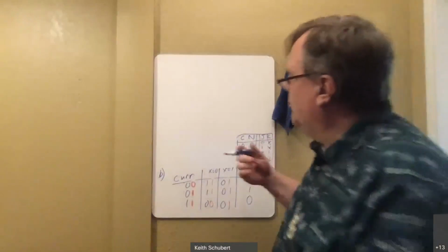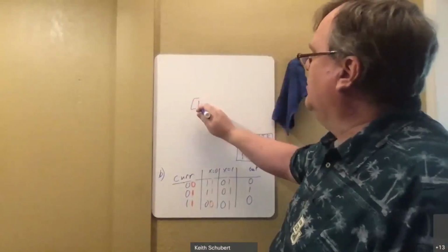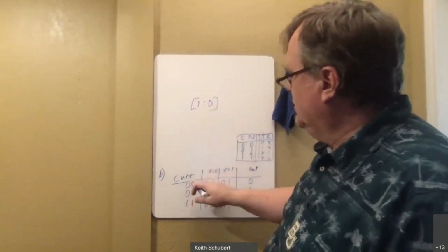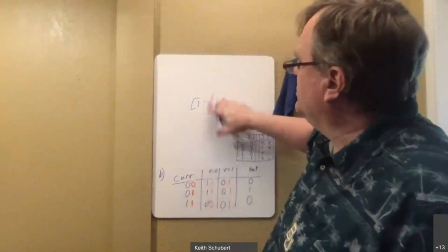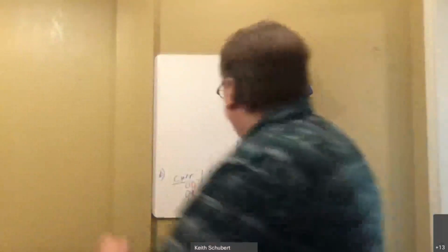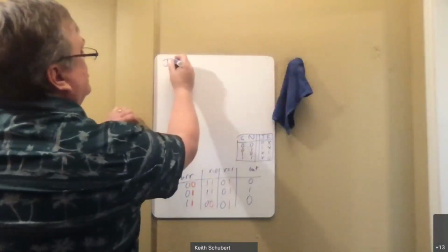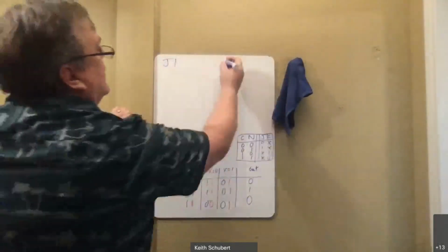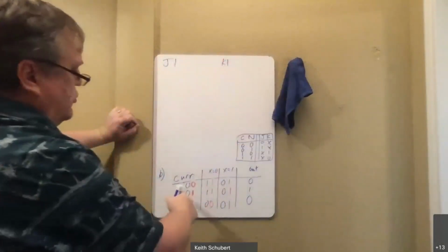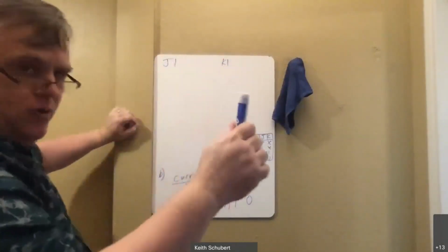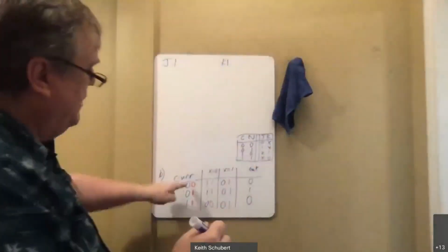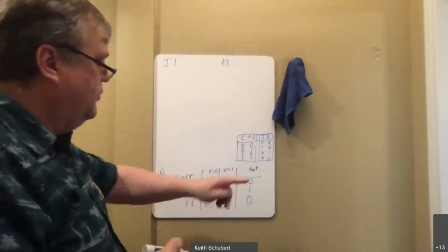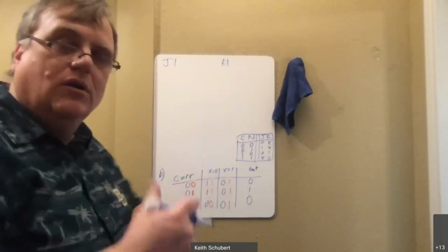If you remember when we're doing this inside Verilog, we sometimes number them like this. It would be like 1 to 0. That means the left one is bit 1, and the right one is bit 0. So we will often use 1 and 0 as the label. That's how I'm going to label my J's. This will be J1, which means the J for the most significant bit. And I will have K1, which is going to be the K for the most significant bit. And I'm doing it in the blue pen so that you know I'm only right now worried about the most significant bits. We're going to do one for the blues, and we'll do one for the reds, and then we move on. So far, so good.